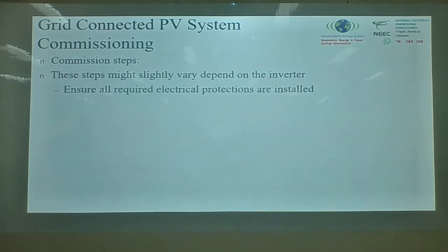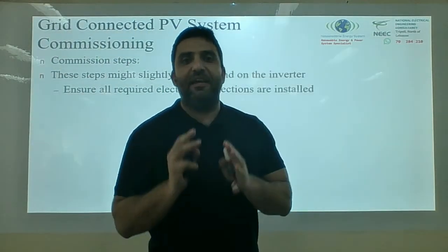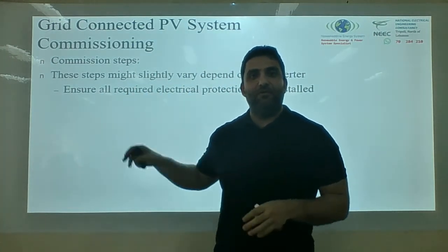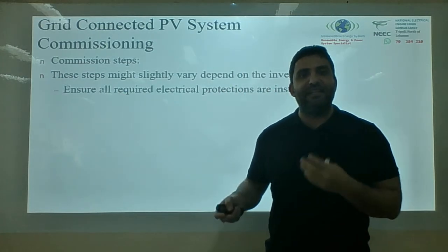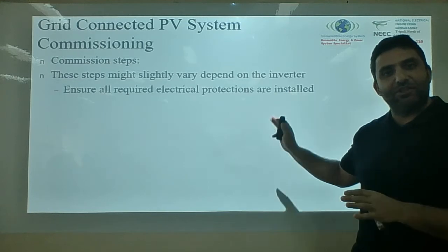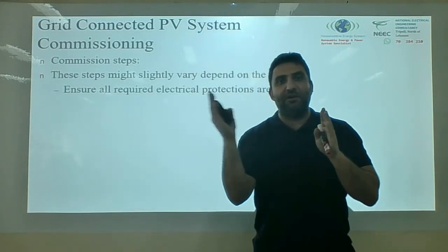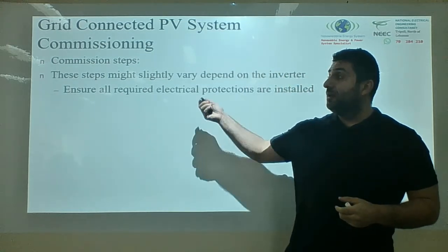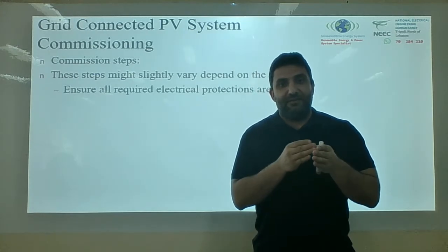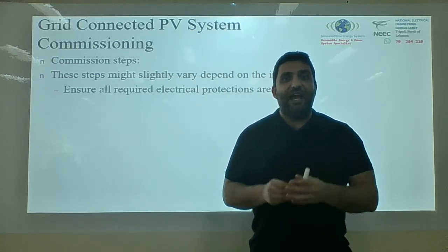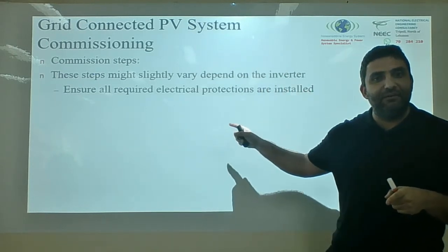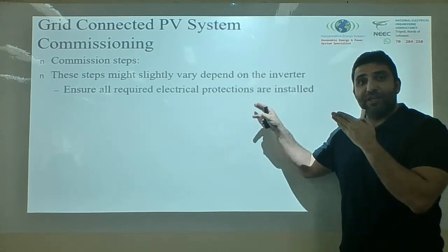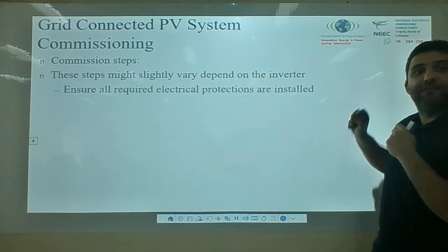Ensure all required electrical protection is installed. We will designate a separate lecture at the end to do the single line diagram for all the protection required on the AC and the DC. The aim of this lecture is to give you an idea about the sun orientation, which will stick with us for the remainder of our lectures. How to connect in series and parallel, what will change, how to read the data sheet of an inverter, and what element of the inverter I'm interested in, and what element of the inverter is related to each element of your solar panel.